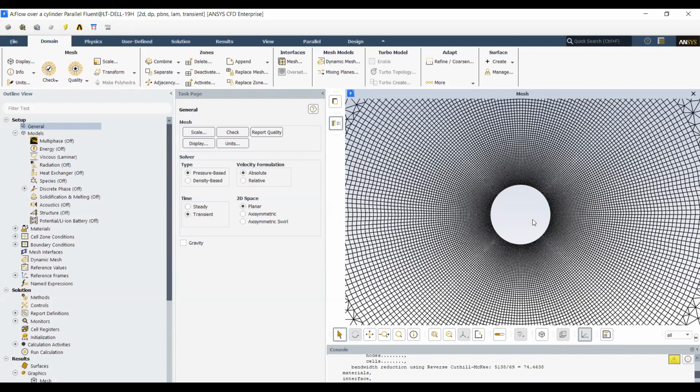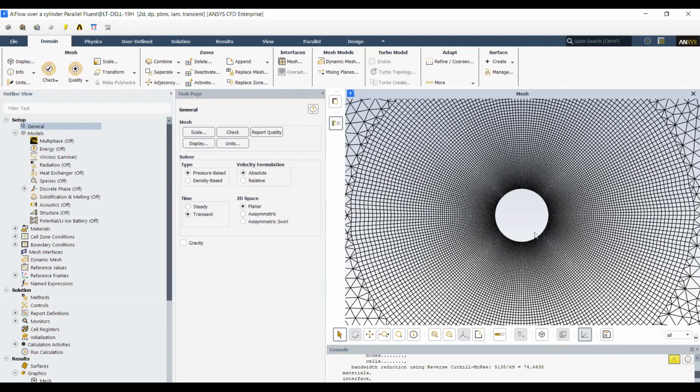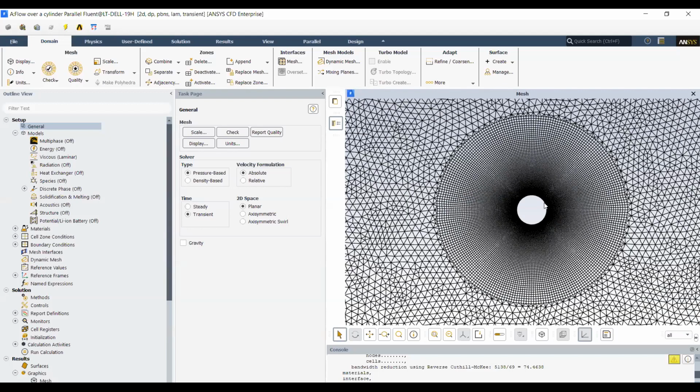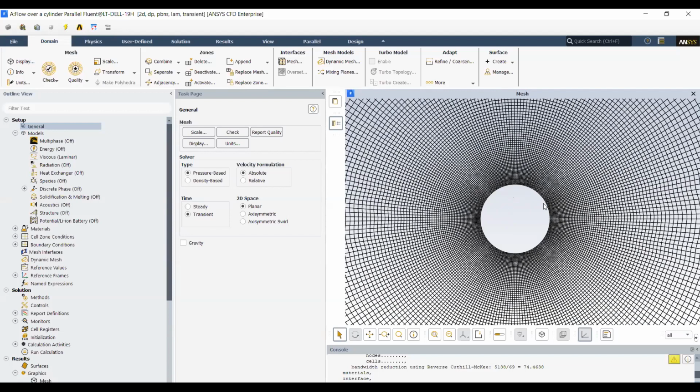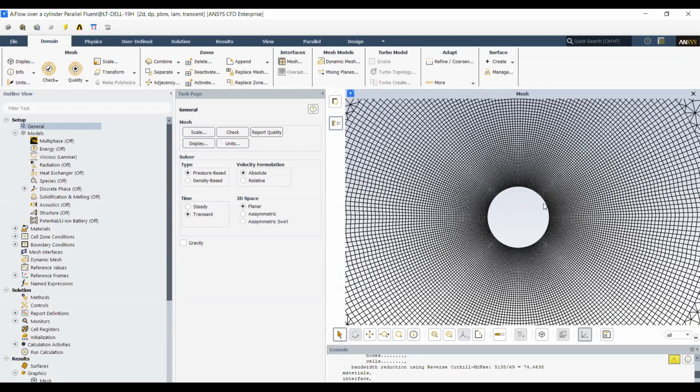We generate a mesh around the cylinder body because we are simulating an external flow. So the flow is going over the cylinder and we want to see how it behaves over a standard set of time and how the pressure and the velocity change. Maybe we can calculate some forces that are acting on the cylinder, the drag and the lift.